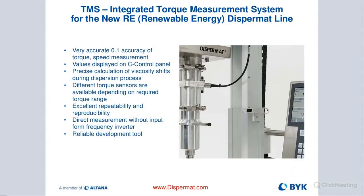You can see that right here on the picture, attached to the shaft. We are measuring very accurately the exact speed of the shaft as well as the power and the torque value. All that data is transferred over to our control panel, and we can visually see the exact precise values of these measurements, much more precise than we would get with the standard frequency inverter readout.